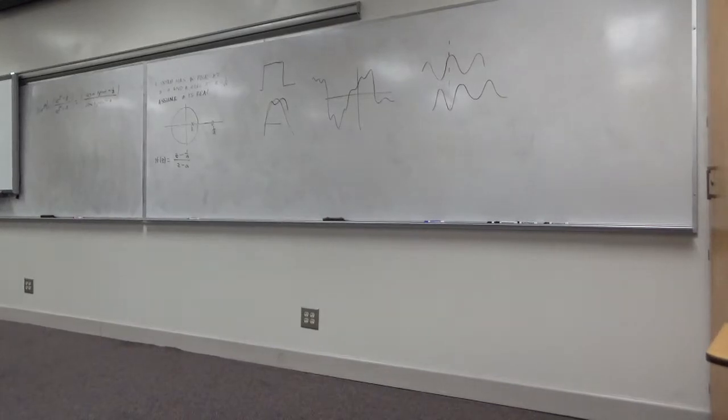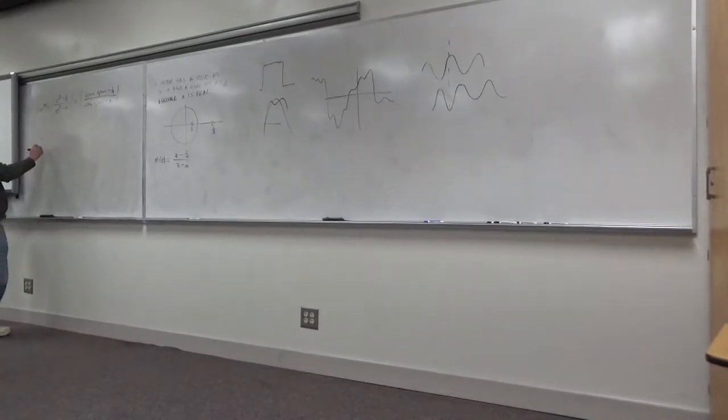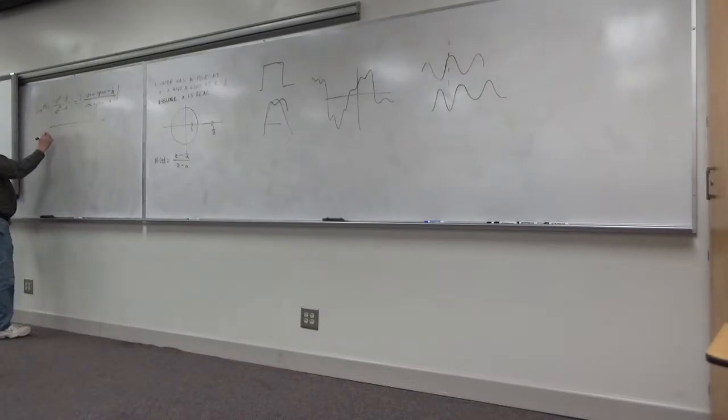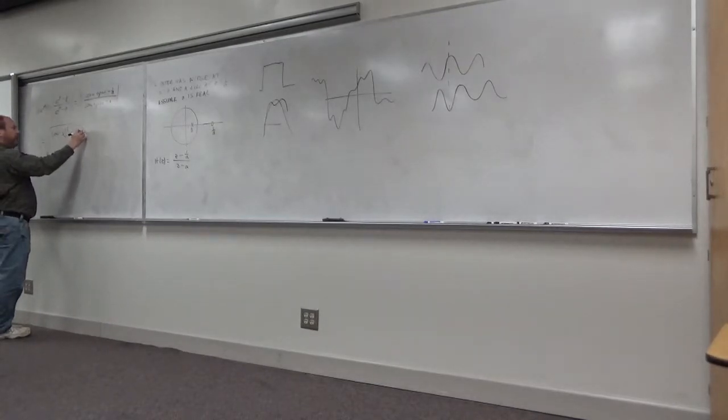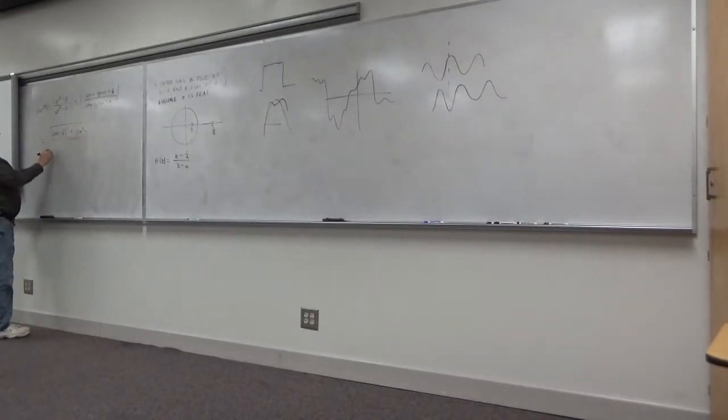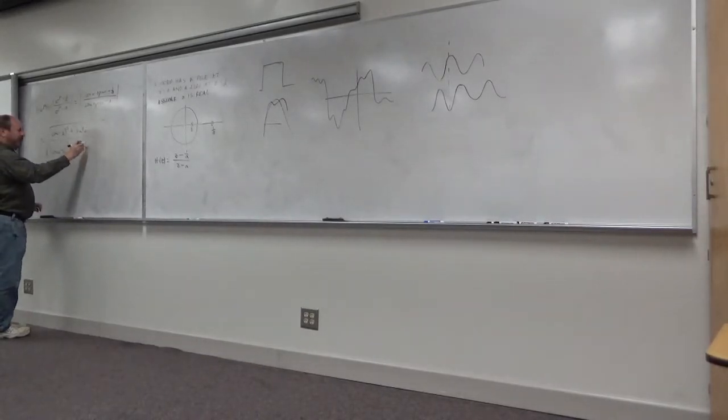There's a few steps here before anything. You'll look at it and say, this is just getting more and more complicated. And it will for a few steps. I want to take the magnitude of that. How can I do that? Notice I've got numerator in rectangular form and denominator in rectangular form. How do you take magnitude? Real part squared plus imaginary part squared. Okay? And then take the square root. That'd be the square root of all this. Cosine omega minus 1 over a squared plus sine squared omega. Denominator would be cosine omega minus a squared plus sine squared omega.